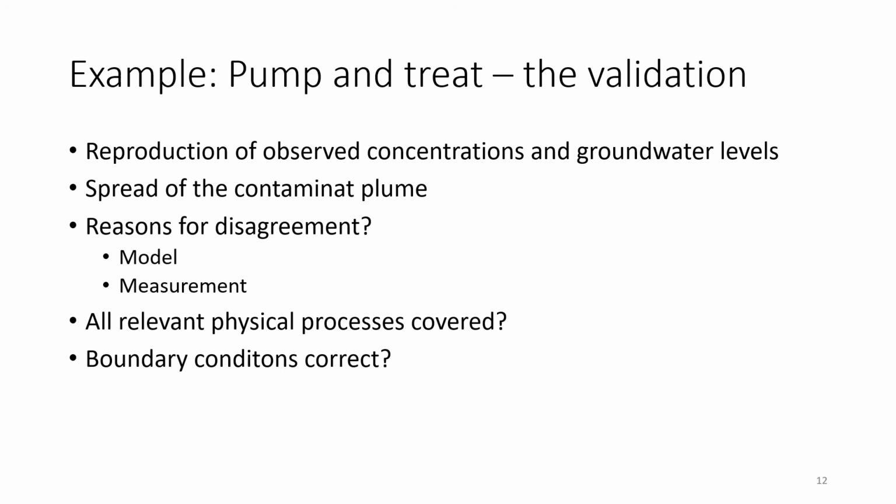Just a little bit of change in hydraulic gradient will cause different flow velocities and might even change flow direction, things like this. And of course, you always have to ask, okay, do I cover in my model all relevant processes? As I said, if I have a contaminant that is more dense than the water and it's sinking towards the bottom of my aquifer, maybe, for example, then my observation wells aren't deep enough to cover all this, and the contamination is actually much higher than estimated.